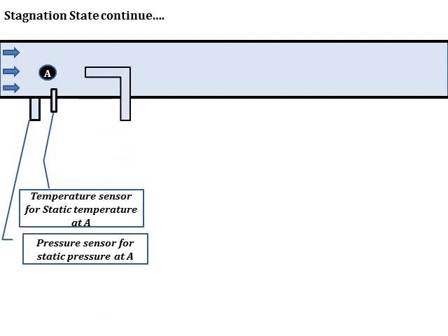Now, in order to obtain the stagnation condition at point A, we have to isentropically decelerate the flow to zero velocity at zero elevation. So, we insert a pitot tube at the same elevation as that of point A, and the pitot tube is connected to a reservoir. The flow, when it hits the inlet of the reservoir, gets decelerated to zero velocity, and we obtain the stagnation condition, which is represented as 0A.